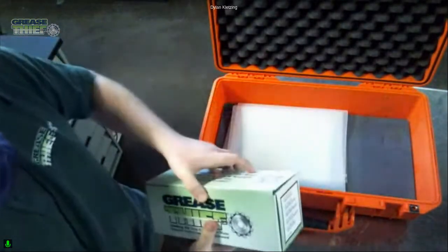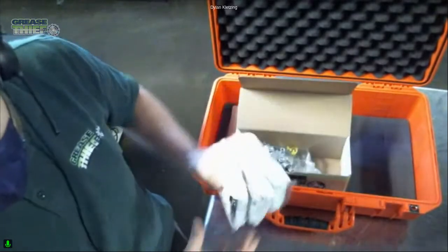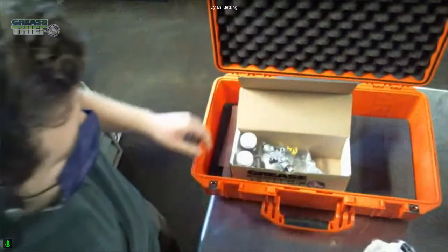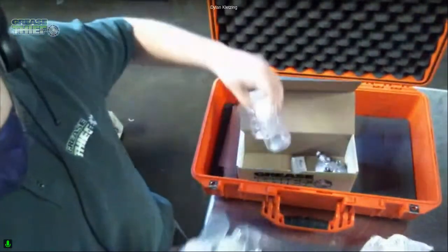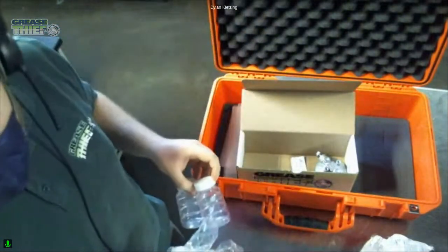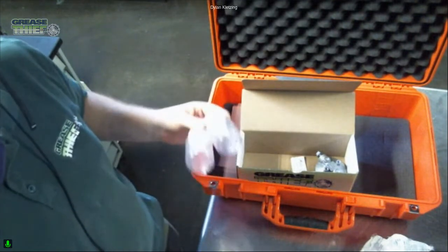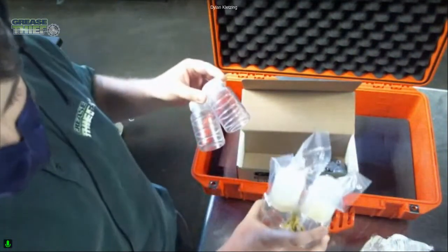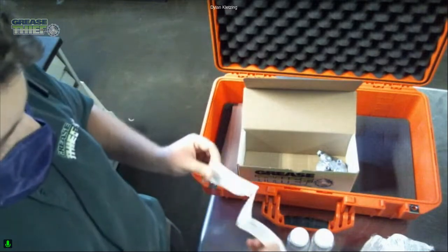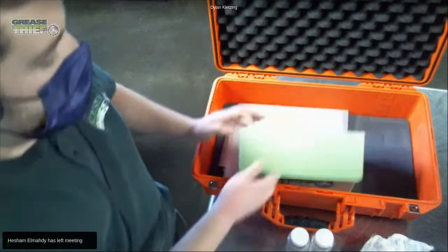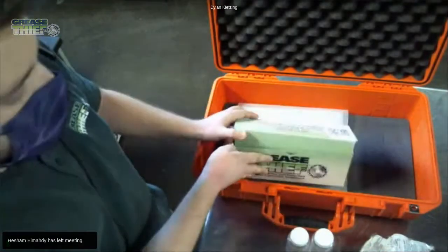So inside the kit also, we have this box, kind of an oil analysis type kit. We do have these 3 sealed air Instapacks to help with shipping filter, but then we also have our vacuum oil bottles and our regular high temperature oil bottles too. This is for oil sampling because, as was mentioned earlier, we want to take oil samples as well with filter analysis because it gives us an idea of the condition of the oil before and after filtering. So these are also important. Inside we also have some labels here that you can put on your bottles. And then on the outside, we have a QR code with instructions on how to use the kit, how to use the sealed air Instapacks as well.